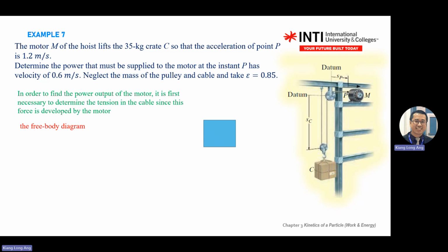So you draw a free body diagram on the mass, then you draw the 2T, like what I wrote on the whiteboard. So you can find what is the tension inside the cable. Right? It's half of your W. And I'm combining the F equal to MA diagram. So the one on the left will be your force, the one with the red arrow will be your MA. Okay. Then your datum, going down positive.